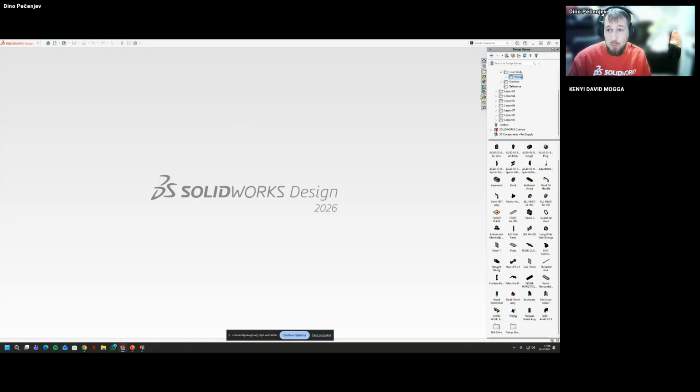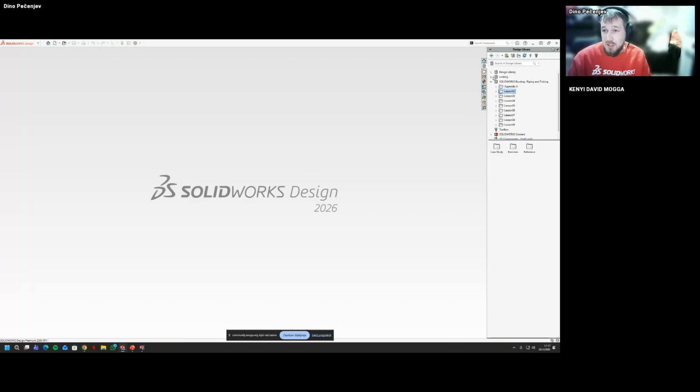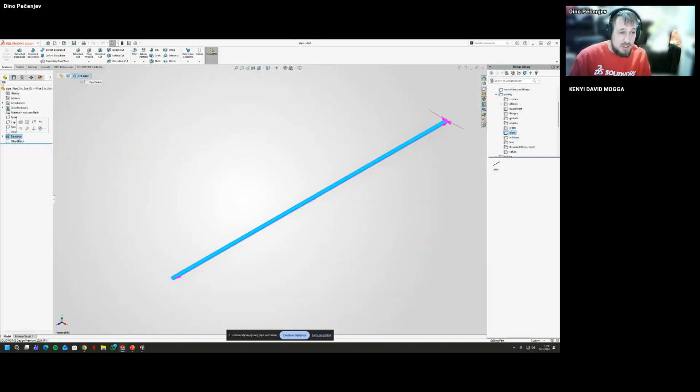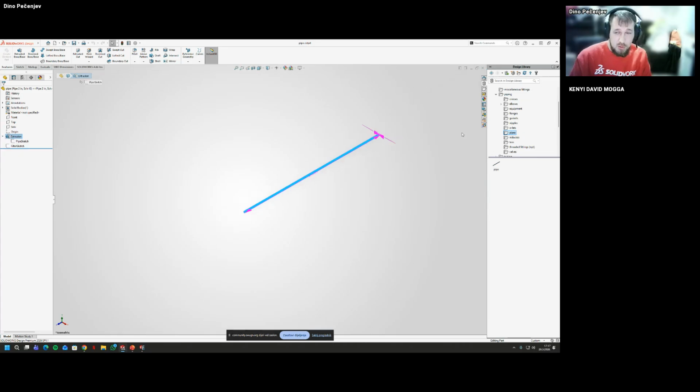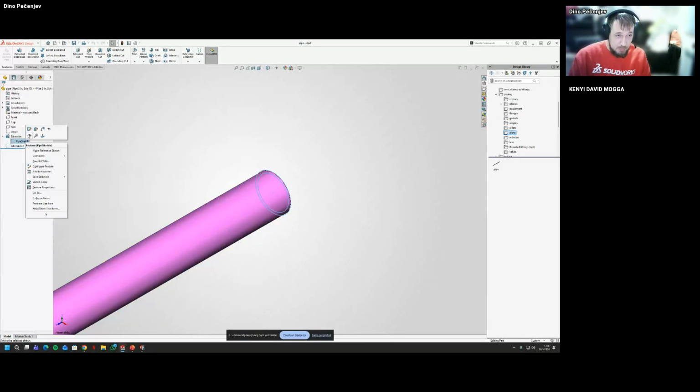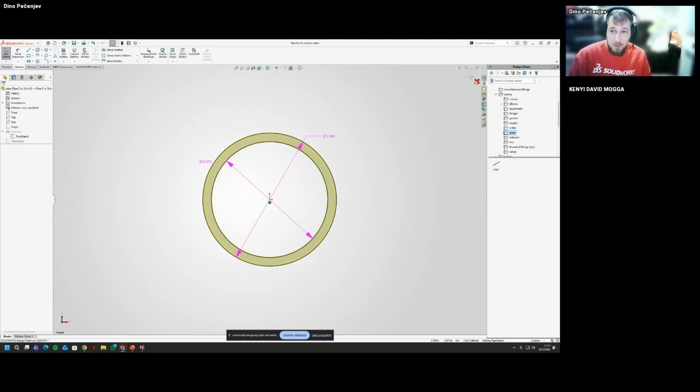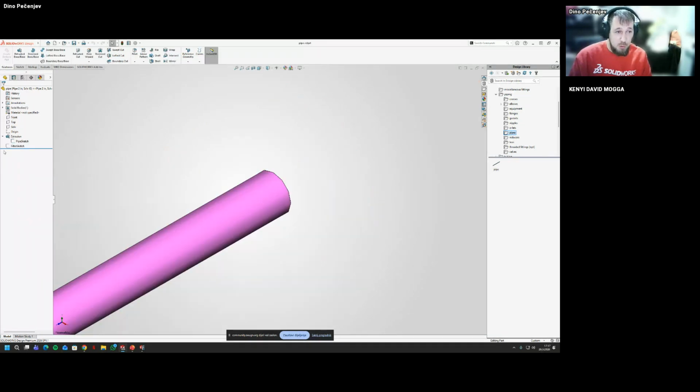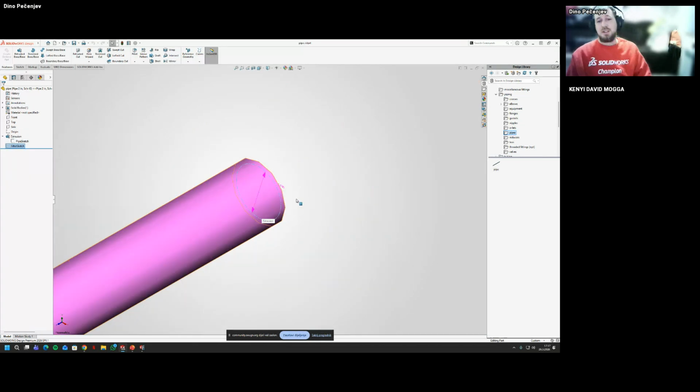Okay. What we're going to do, I'm going to open up a pipe, which is the default one in the library. So, and let's say for this pipe, see, this is extrusion, just to take a notice of the sketch. So this is why the piping is rigid and it cannot be flexible. So it has a pipe sketch, which is already defined, and it can be easier for us to manipulate that when creating new pipe. And we have a filter sketch. Filter sketch is actually quite important for placing the pipe itself.